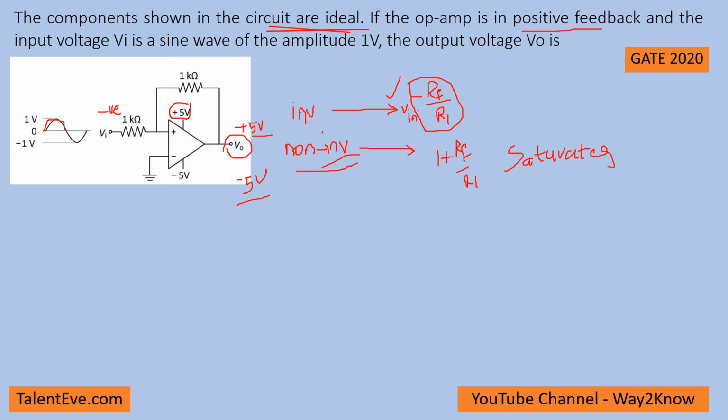So in an inverting configuration, when the input is positive, the output goes negative, and then this is fed back, and it becomes a lesser voltage, and that stabilizes when considering the Rf and R1 input resistances. So that is the difference.